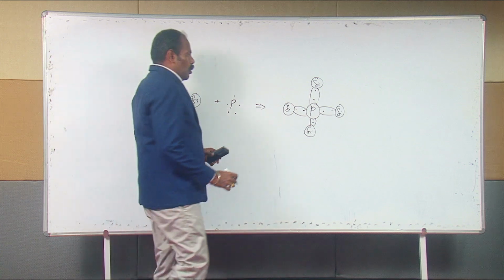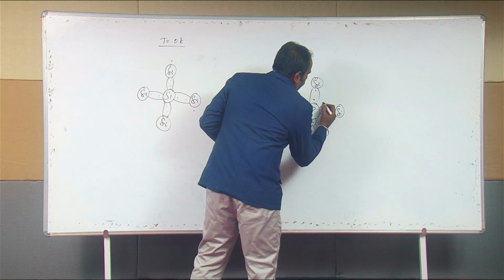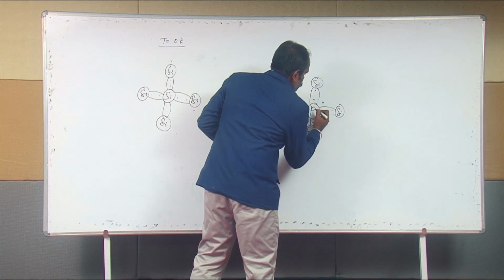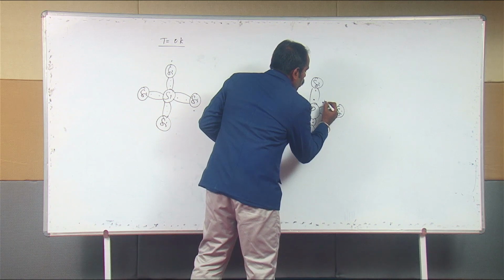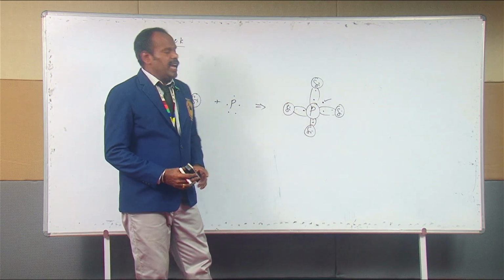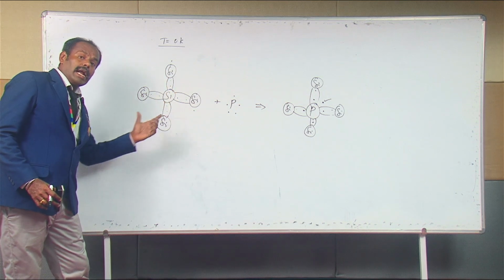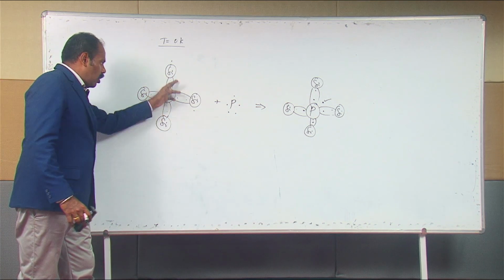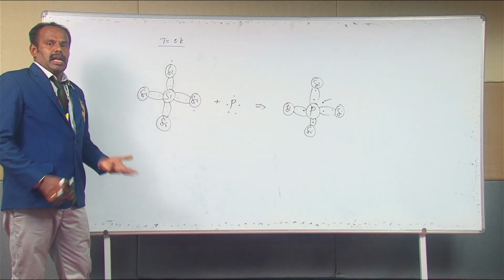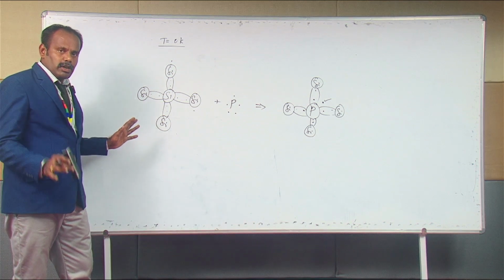Right. Now, what about the 5th one? The 5th valence electron belonging to this phosphorus atom is now newly introduced into the system as a free electron. Initially, there is no free electron when you have the network of silicon atoms alone. If there is no free electron, it simply means that the electrical conduction is going to be nil at T equal to 0 Kelvin.